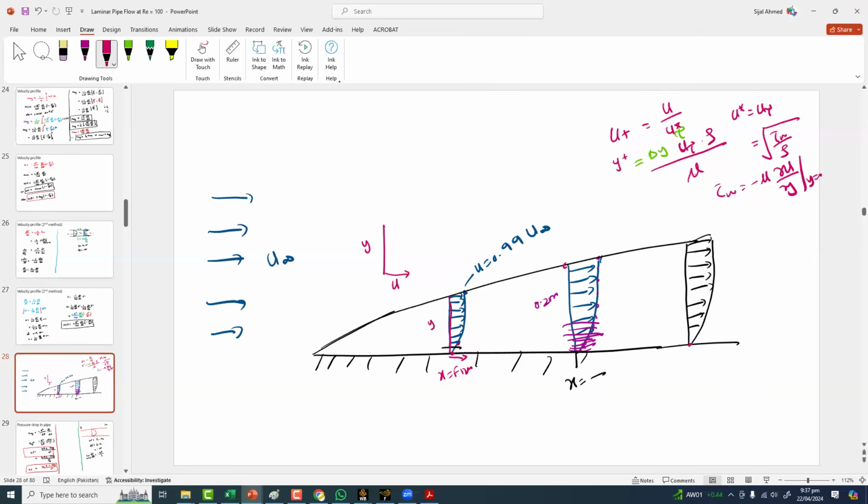They're talking about the first cell height of your cell here, and they talk about the friction velocity, which is the velocity very close to the wall. So let's say you are talking about y plus equal to 1. You know that the density of the fluid is known, and so is the viscosity. Now for mu t, if you are solving it, you know the value from simulation, but let's say you haven't started the simulation and you want to get an idea of the first cell height.